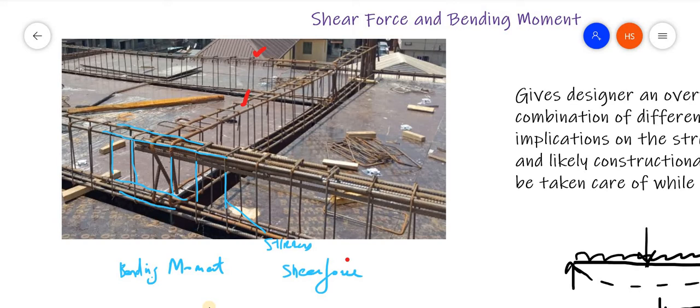While designing any structure, the first important thing to understand is the different modes of failure, how it can fail. Only by knowing how it fails can we give provisions to prevent that failure. In order to prevent that failure, we give these types of reinforcement. This is the way you have to think.